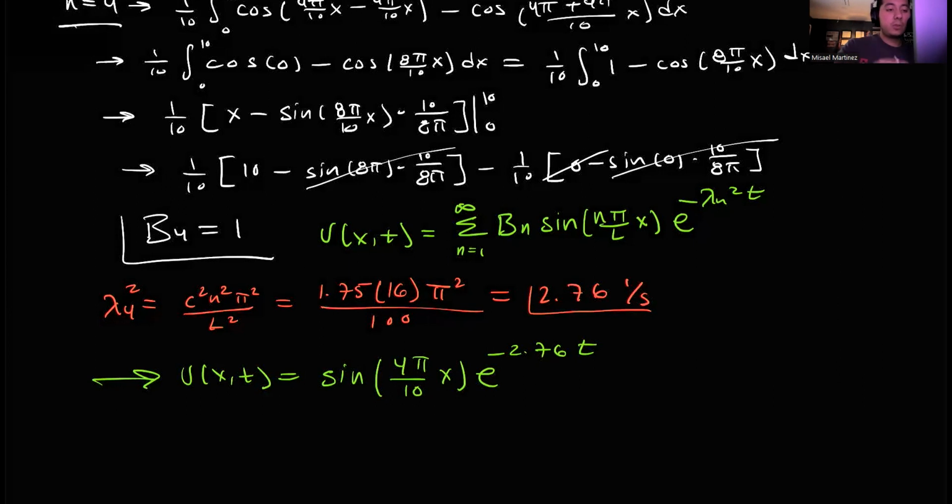So you're going to put this equation in MATLAB. You can make a matrix for x, a matrix for t, and keep in mind that for x it will be a matrix from 0 to 10. We can do it in increments of 0.1 all the way to 10 if you want to. And then we need another matrix for t from 0 to 2 seconds.